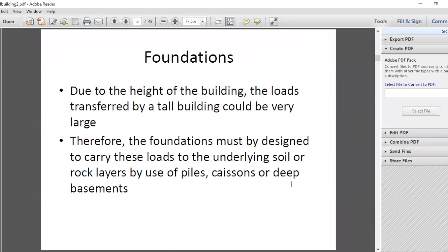But at the same time, certain locations, you will find that the soil conditions in the top layers can be very bad. Sometimes you get peat layers and so on. So in such situations, you have to be careful to assess and see whether the negative skin frictions can develop and add more loads onto the piles.